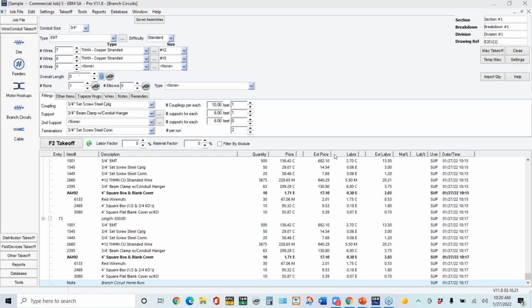For receptacles, you'd have to add 8 to 10 feet. And again, it all shakes out at the end. It's going to be 15 to 20 feet per item. The adjustment is important if you want to check the math, but the whole idea is that the 15 to 20 feet is going to hold true for most commercial jobs.